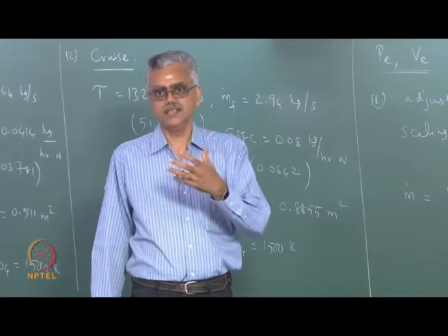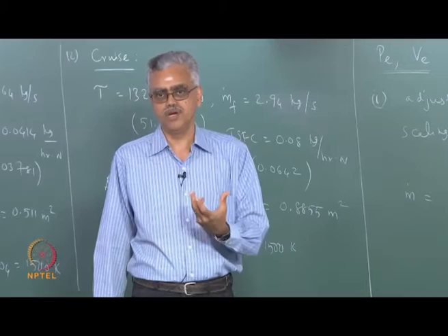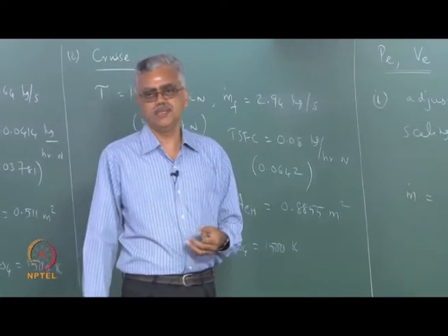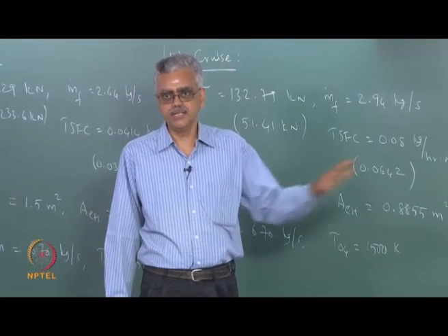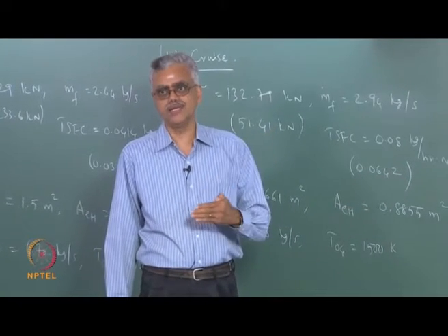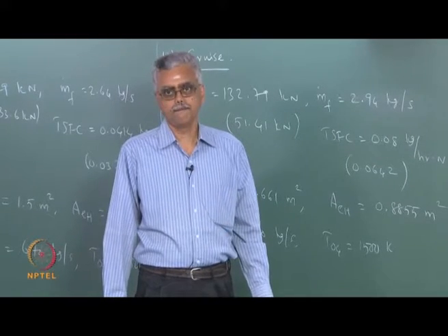So an engine does not always operate at the same mass flow rate. Mass flow rate through the engine can be changed by adjusting the speed of the compressor and fan. That is quite possible. That is what we are proposing here, that the engine should take in less mass flow rate. But the engine is cruising at the same speed, no?